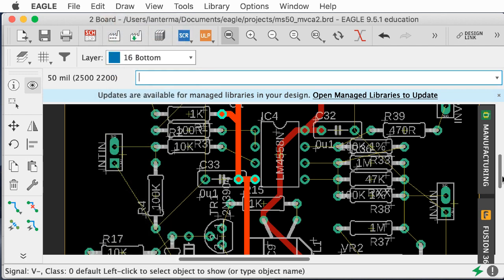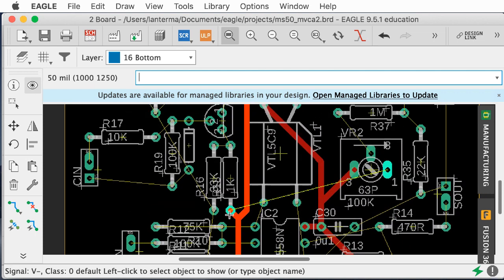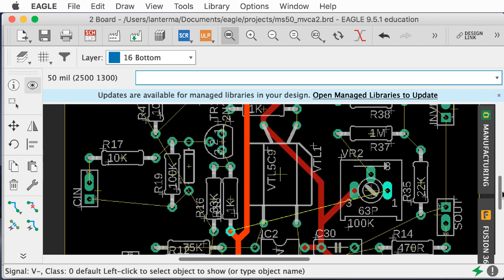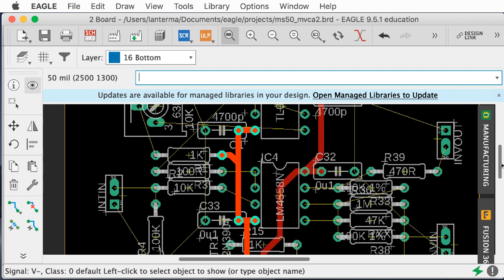That's the bottom layer, and that's where I like to generally put ground if I can. Now, I will switch layers if I need to, in order to make the routing work. If I need to temporarily switch one of these to the blue layer, switch top to bottom or bottom to top, I'll do that, especially when it's convenient to make those transitions at a particular junction point. Now, in general, I try to keep things on the same layer, and I try to avoid putting in a lot of vias where I switch one layer to another where there's no through-hole part where I'm doing that anyway. Especially compared to the auto router. The auto router will just kind of throw vias everywhere.